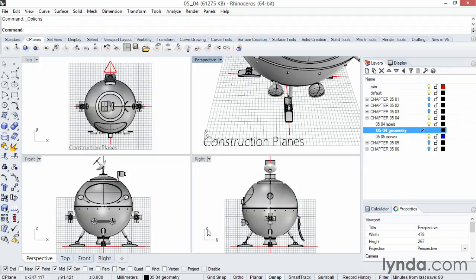The second rule is that the construction plane is your default location for anything you do, whether it's creating geometry or moving geometry or rotating it, except for if you have O-snaps on. Then it will use those O-snaps to move it or align it with those settings versus just going on the construction plane. So think of your construction plane as your default location when there's no O-snaps telling it where to go. I'm going to demonstrate this feature.